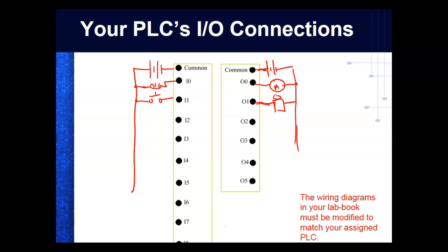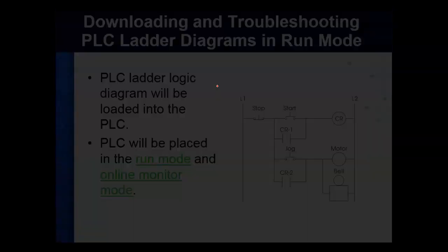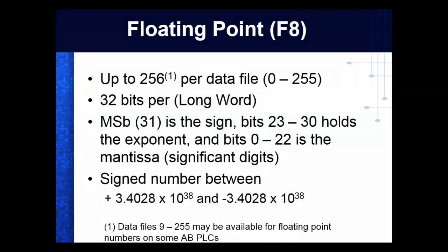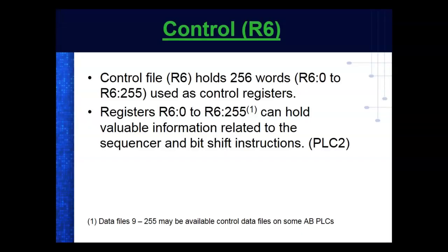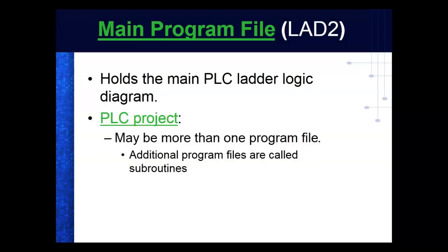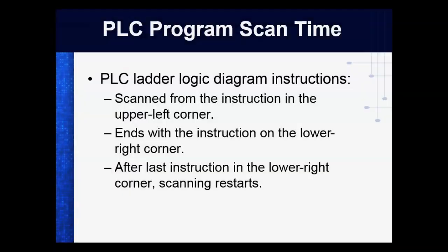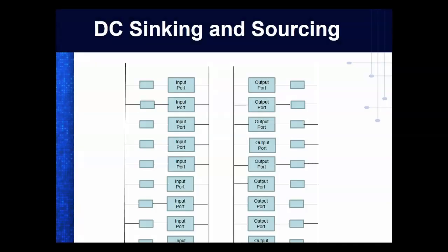It's kind of different, and I'll show you how it's actually wired up when we get to our PLC. The problem is that if I do it like that, I don't establish what the common is right here. So this is the way it actually works. I come up here and the power source would actually be connected like this. Let me get back to this where I have these sinking and sourcing things. But that's a really good point. But to actually see it, we'd have to understand this guy right here. So this is the way we do it.